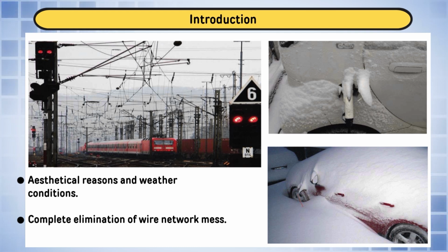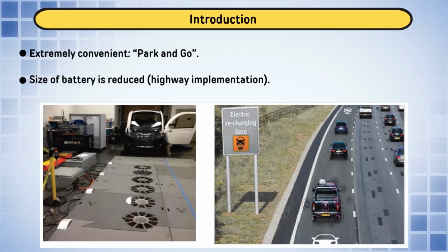We have taken the input voltage and input current from the PV module or from the wind based plant, and then these input voltage and current, PV voltage and current, are supplied to the MPPT control. It could be incremental conductance based control or some perturb and observe based control, which is generating the duty cycle at a certain switching frequency to control these DC-DC converters.